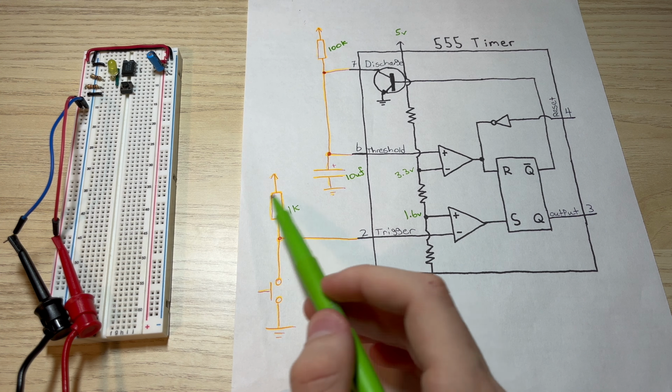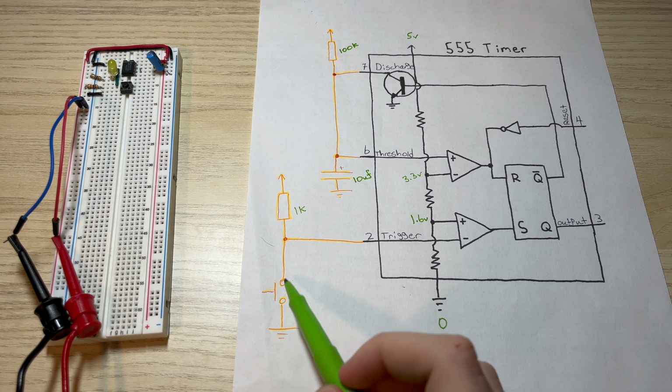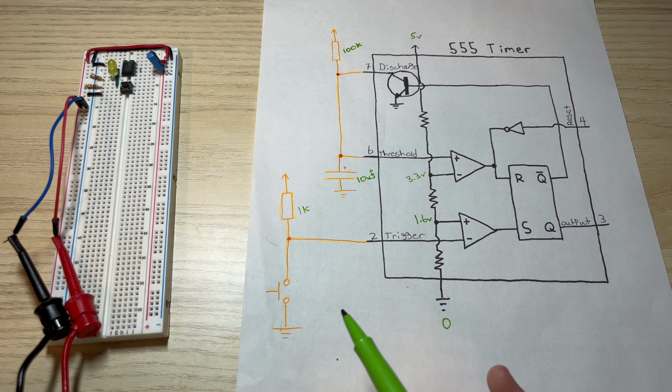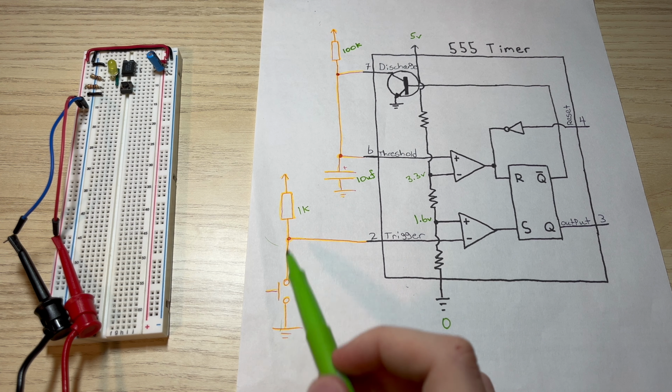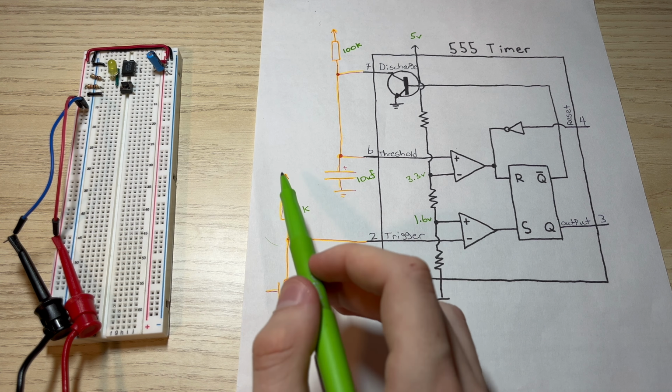Let's take a look at our peripheral circuits real quick. We have a 1k pull-up resistor. If you don't know what a pull-up resistor is, basically we have a push button here connected to ground, and since our signal is going to be 0 volts, we're tying this high. While this is not pressed, this is just tied high. When the push button's pressed, instead of going through this resistor, it'll go through here, so this will just be totally ignored. We'll talk about these two later, but these control the duration of the output.